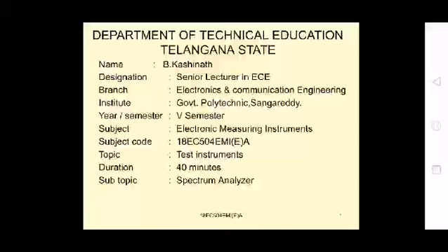The impedance converter has low noise and high input impedance, such that the source impedance will not affect the distortion factor meter instrument. That is the main advantage of the impedance converter. It is a 1:1 converter having low noise and high input impedance. That input impedance will not cause any loading effect, whatever may be the impedance of your source. Then the output from the impedance converter goes to the rejection amplifier.